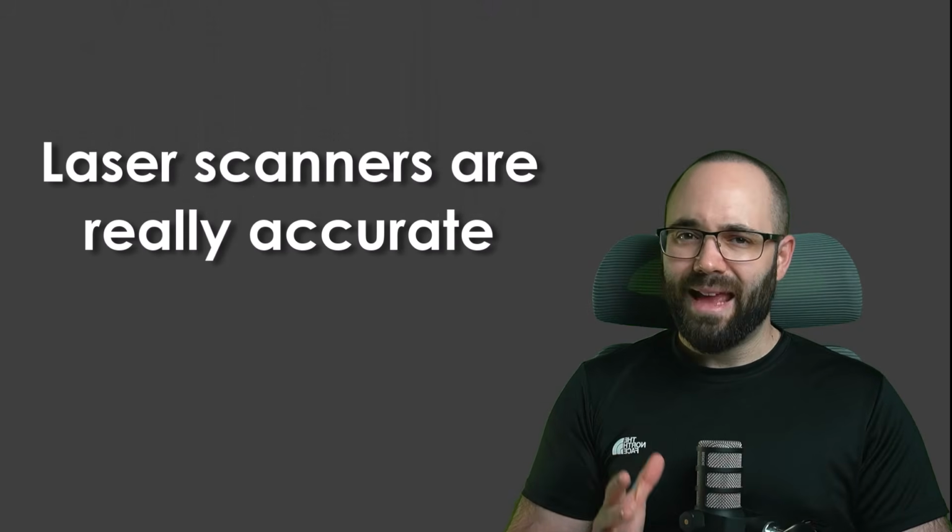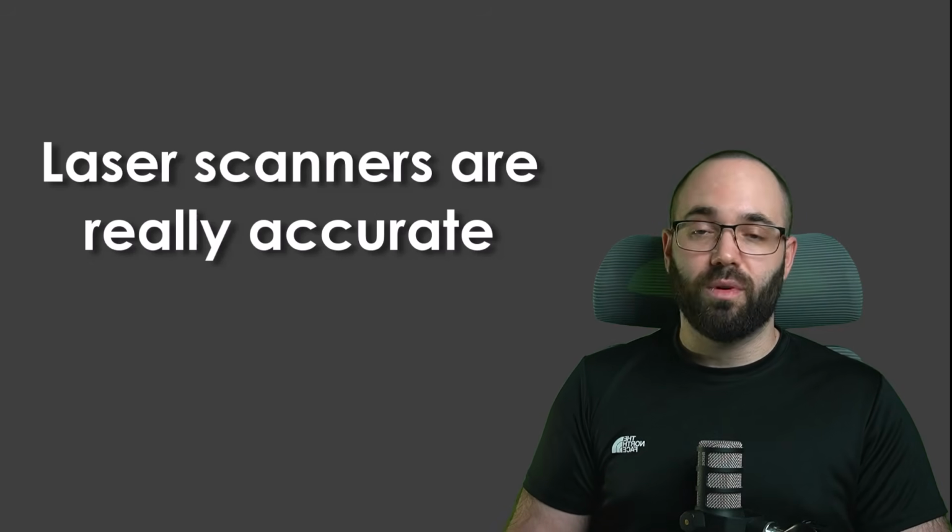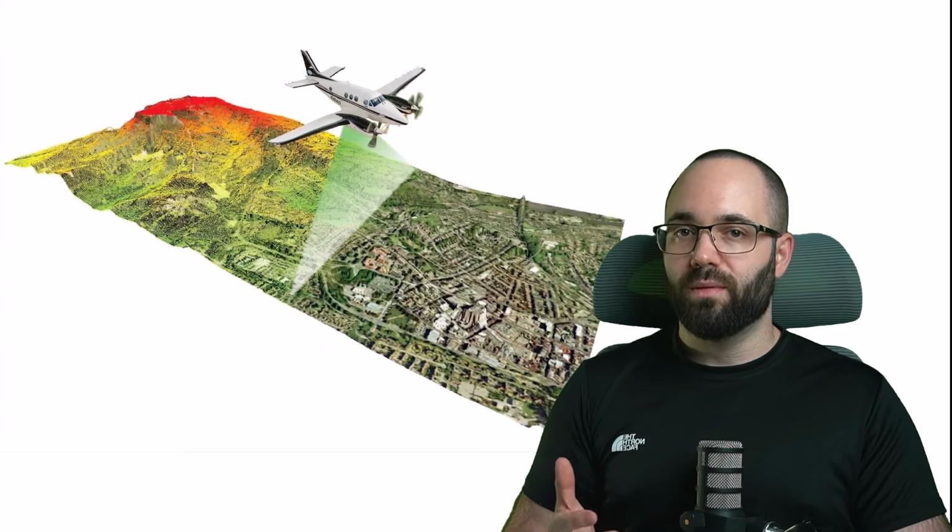Laser scanners are really accurate. They can capture data down to a few millimeters, and this is perfect for complex buildings such as heritage structures or irregular surfaces. These scanners can be mounted on flying objects like planes or drones. Alternatively, you can place them on a vehicle like a car, train, or trolley. And finally, we can just place them on a tripod and move them around from spot to spot by hand. For architecture, you will usually see drones being used for the exterior of the building and then terrestrial or just tripod-mounted scanners for the interior.